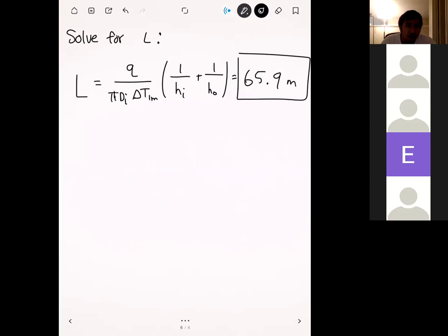It would affect the fluid mechanics a little bit, and so the flow patterns would of course be different as you go around the bends. But as long as it wasn't making an S formation, so as long as you have a relatively straight part in a bend and another relatively straight part, then I would expect the bends not to affect the calculations all too much. The reason for that is if you still have a reasonably long straight section, then the flow has time to develop into its fully developed state, and in those cases the bends don't have too much of an impact. Yeah.